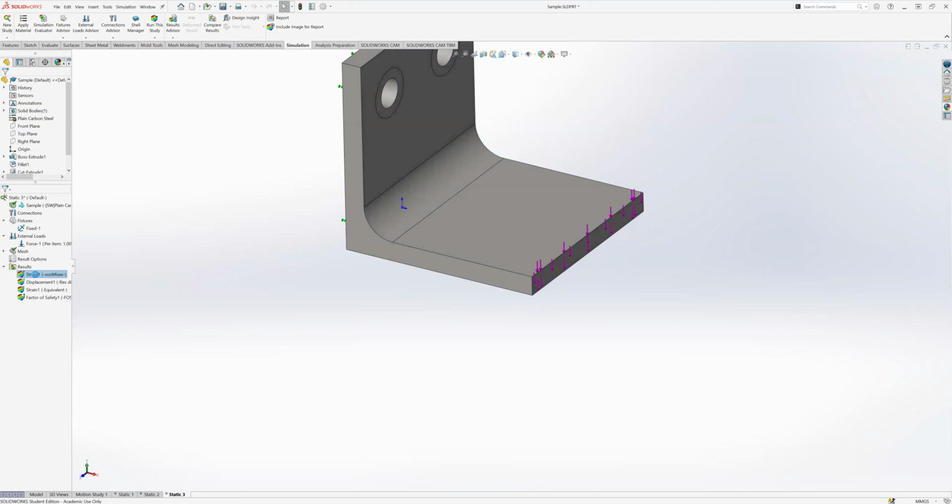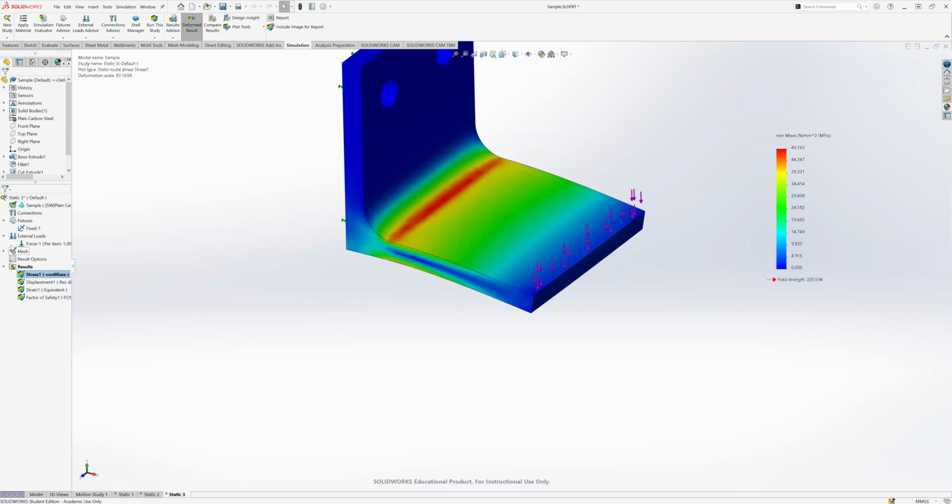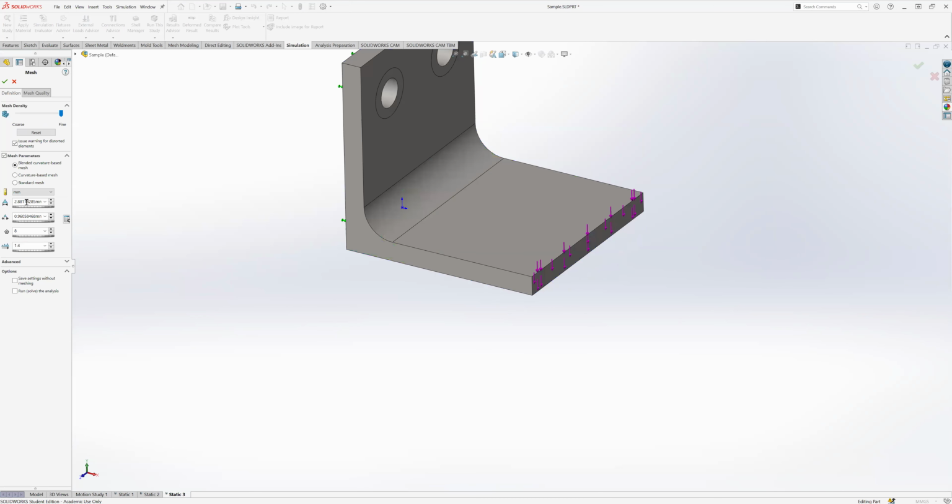And again, if we go back to this, let's say I really do a fine mesh. I'm just going to modify this same study. Let's do create mesh. Right now we're at a maximum element size of 2.88. Let's just crank it down to like 1.72 or something.